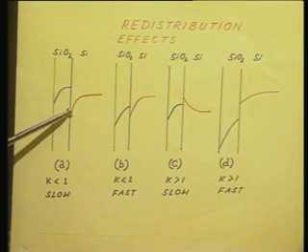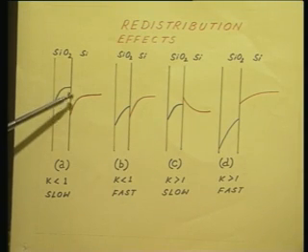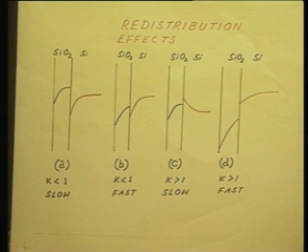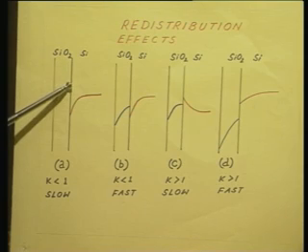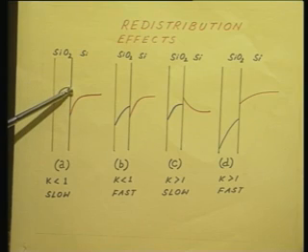Near the interface, the boron concentration is less. Do you see that? This is because of the fact K is less than 1. Now, the boron profile inside the silicon dioxide, at the interface, this concentration should be higher on the oxide side. That is because K is less than 1, equilibrium concentration of boron in silicon dioxide is high.